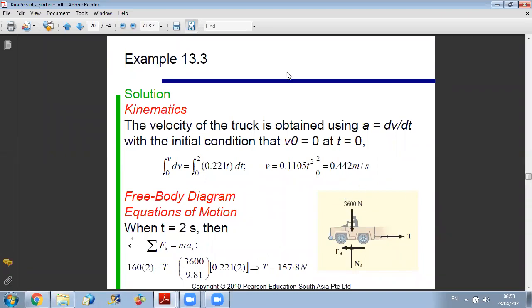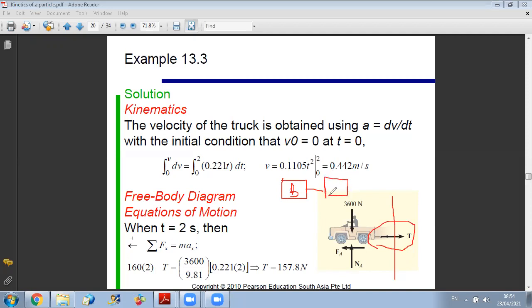B. So as we already talked about, the coupling force is internal if I take the whole system. So for this force to appear, I should do a cut between A and B. Then when I perform the cut, I can take either A or B plus C. Both will give me the same result. And if I take B plus C, then the free body diagram will be as follows. I will just have the coupling force acting on it.